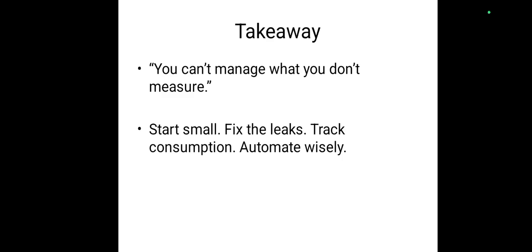I wanted to tell you something. In our commercial building, I studied the employee login and logout times, and whenever they go for a long break like lunch, I turned off the AHU in the BMS. Also, in our reception, a triplex area where the AHU was running unnecessarily, I turned that off too.